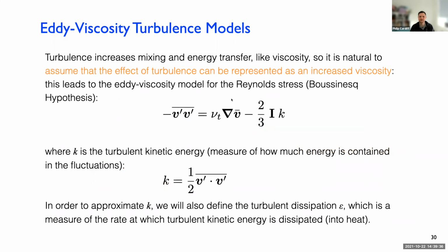So the idea for the K epsilon eddy viscosity approach is that this Reynolds stress term is described in terms of the average velocity by something called turbulent viscosity. Turbulent viscosity is not a real viscosity, it's just an addition to the real viscosity as a function of these smaller eddies. So it's like the apparent increase in viscosity caused by these eddies, basically. And it's also a function of K, the kinetic energy of these smaller eddies that you're not capturing on the grid. This is called the Boussinesq approximation. So K here is the kinetic energy of these perturbations, averaged in time.